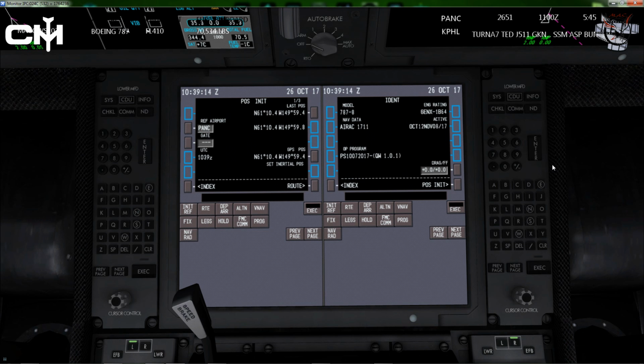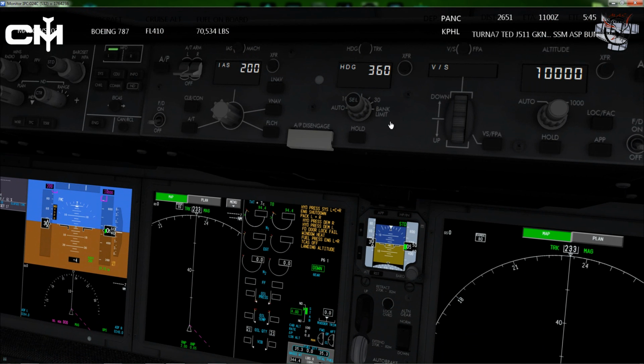The engine display switch, it says to push it. We don't actually need to push it because we've already got the engine information down here, but just in case you forgot, it's this button right here that turns this information on and off. And we want to make sure that we have at least 18 quarts of oil, which of course we do.